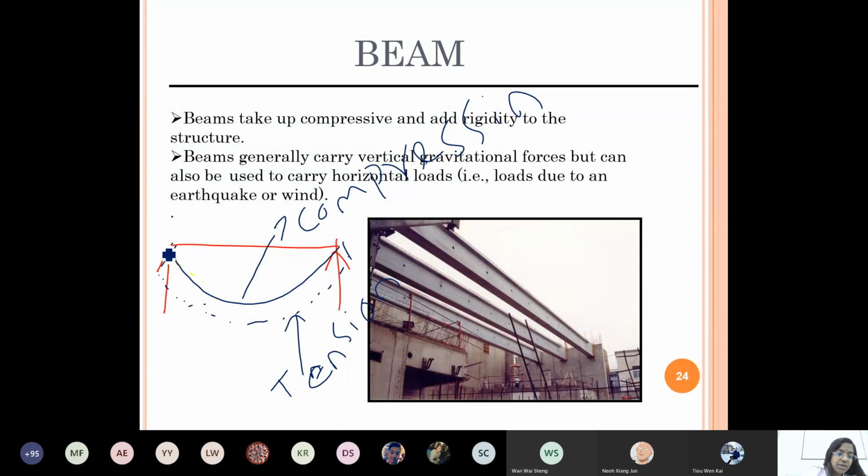What is the beam supposed to be doing? Originally the beam is like this, of this thickness. When it is loaded, it tends to bend in this direction. This is tension, and this is compression, so it needs to take both loadings. Accordingly, you will supply the reinforcement to resist. This member has to resist the load that is coming in, so that it is not bending, or is kept in position, and the structure is always safe all through its service period. This type of failure has to be avoided.